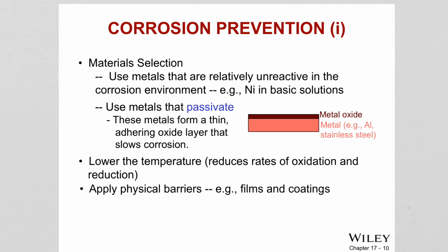Think about the aluminum foil you see every day. Do you ever remember seeing corrosion on aluminum, or an oxide film? No, this film always forms on top of aluminum, and it's very thin. Why does it slow down the corrosion? Because remember, corrosion is actually a diffusion process.